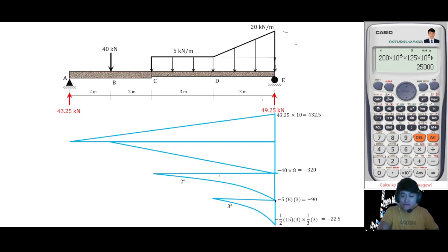Okay, so let's now transform this into a conjugate beam. Anyway, before we transform, let's finalize first our load, or the moment diagram by parts. This is a non-prismatic beam. So we have here a given of 2EI, and this one is only EI.